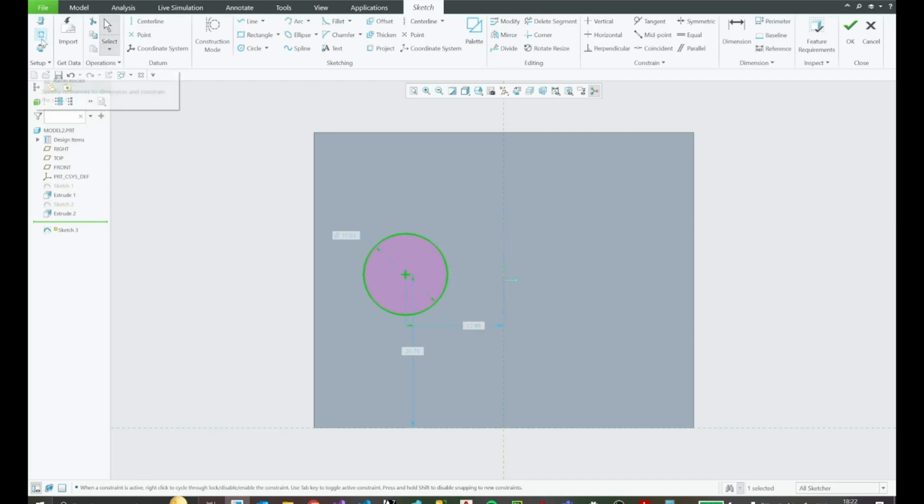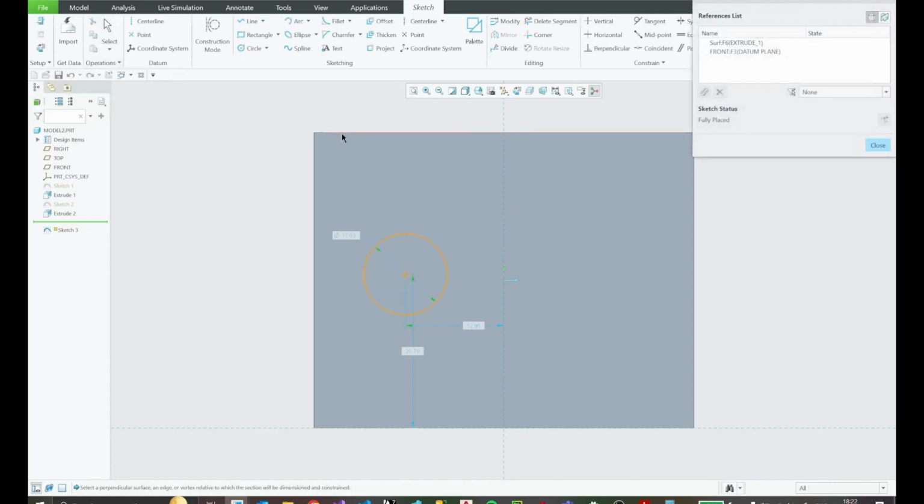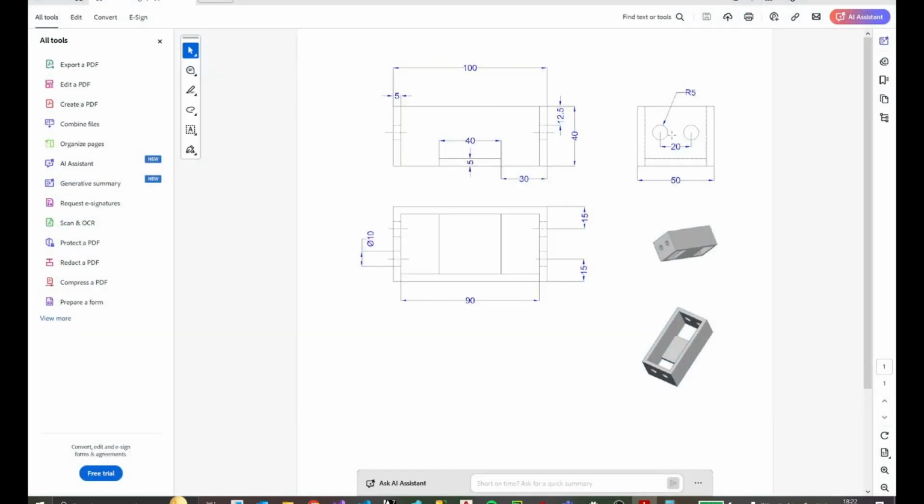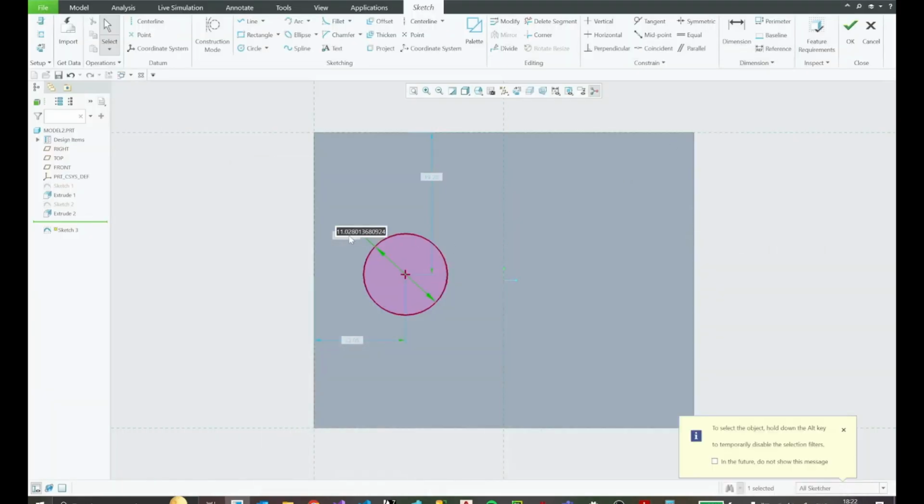So go over here, select the reference, and click this side and this side, and you're gonna make them as references, and click this button to update the sketch, and press close. So now you can see these dimensions are being referenced from these two referenced sides. So on this side you can see the diameter of this hole is 10, or radius of 5, which means the same thing. This drawing is over constrained. We're not going to complain about that. Press make it 10 and lock it as always.